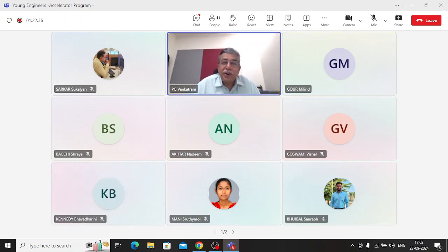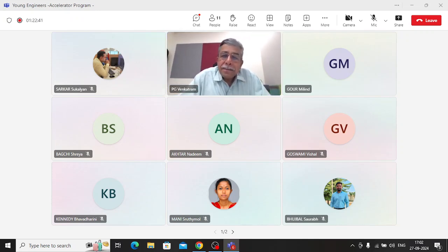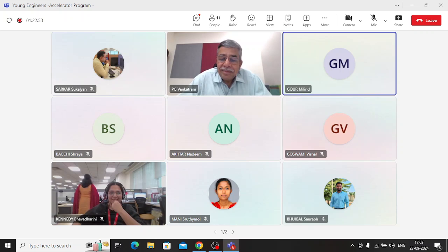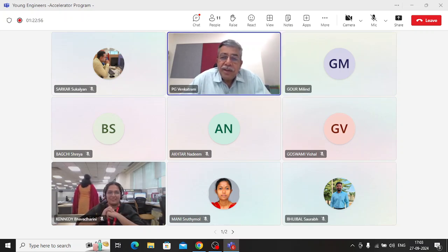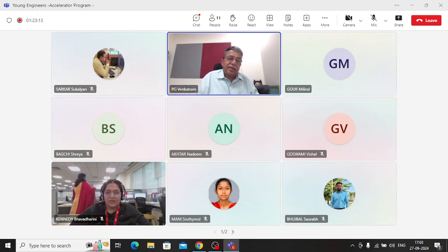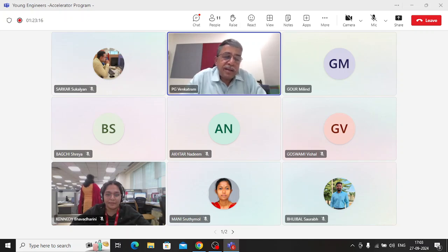Why? Now I'll ask those people who said not possible, why? Any one of you can answer quickly. There is no bending moment typically in an arch bridge if the geometry is right. In a suspension cable, on the cable there is only axial tension. When it comes to an anchor, because of its inclination, it has a vertical and horizontal component. We are talking about the horizontal component. Can I transfer it and anchor it into the deck so that I don't need a strong ground anchor for taking such large horizontal forces?